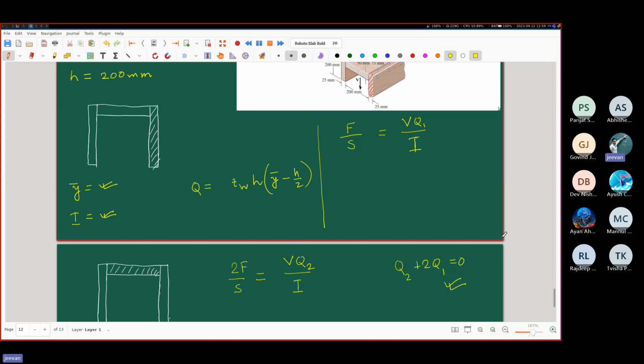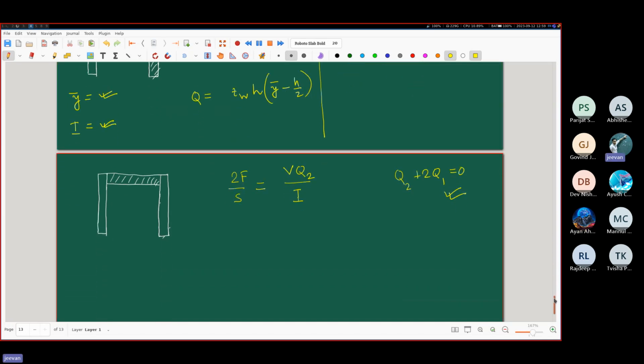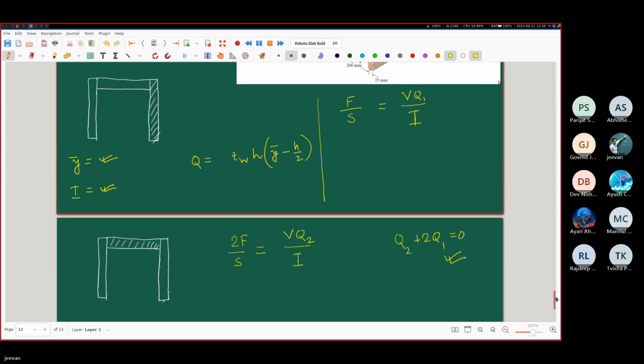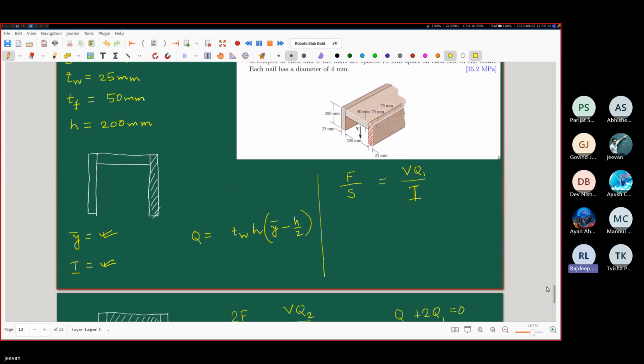for the horizontal board also there will be nails only on one side. And when you do the vertical board, then also nails on one side. So the factor of 2 will not be there. It will still match. So only Q1 we would take in that case for Q. Sorry? So if there were nails on only one of the sides, we would be considering only Q1 as our Q, like I have taken here, right? Yes. Absolutely.